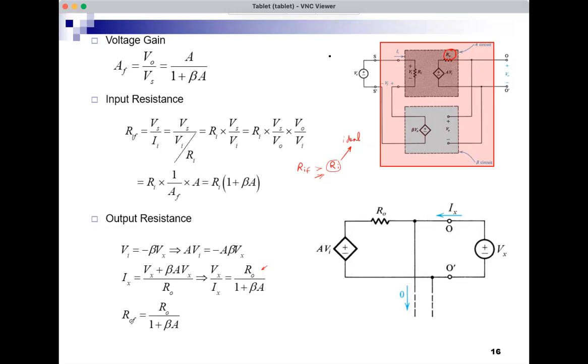If you take the input resistance, apply feedback, and it increases in a voltage amplifier, then it's going in the direction of becoming closer to ideal, and therefore, it's an improvement. So feedback is helping us in this case by increasing the input resistance of the voltage amplifier. For the output resistance, we said that it's less than Ro and possibly much less than Ro. The ideal output resistance of a voltage amplifier is 0, as a short circuit. So the smaller, the better for a voltage amplifier. For output resistance, the smaller, the better.